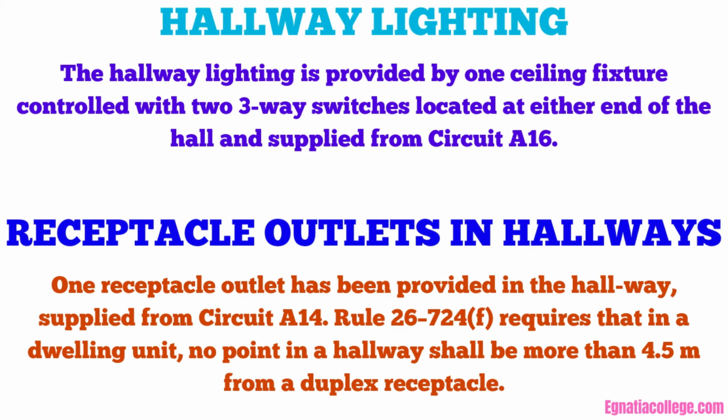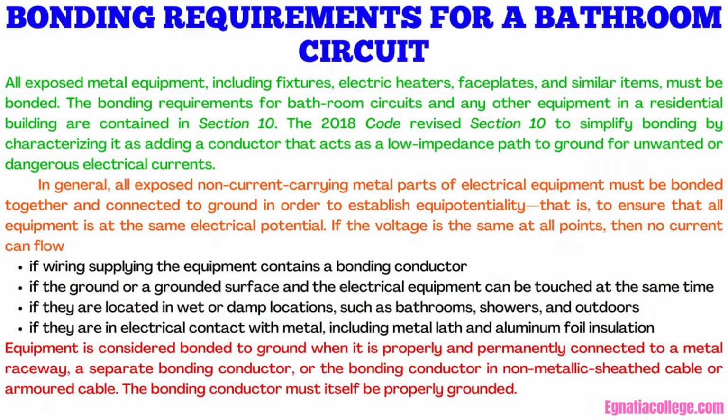Receptacle outlets in hallways. One receptacle outlet has been provided in the hallway, supplied from circuit A14. Rule 26-724F requires that in a dwelling unit, no point in a hallway shall be more than 4.5 meters from a duplex receptacle. Bonding requirements for a bathroom circuit.